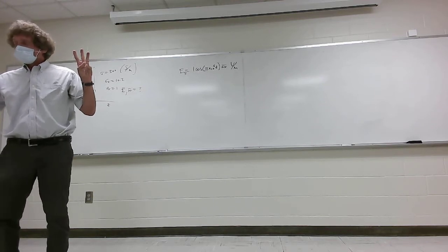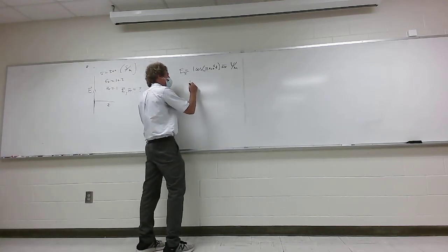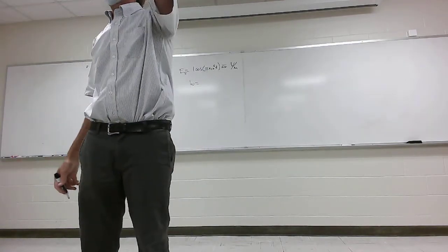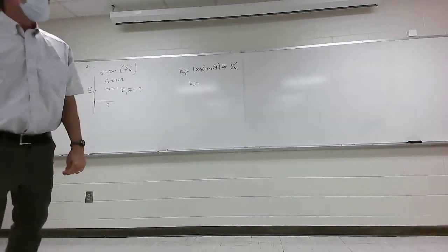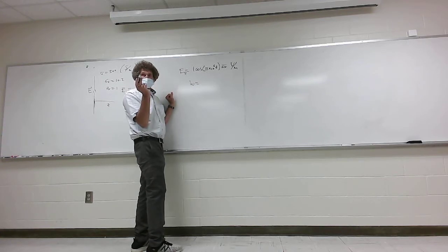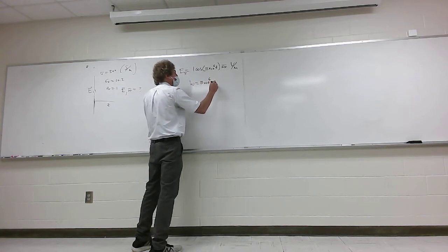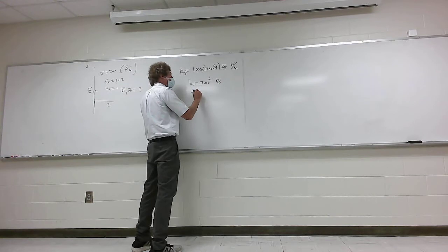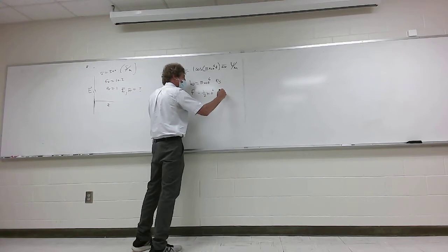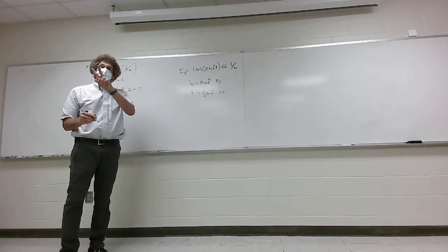Before we do that, we have to ascertain the frequency of operation, omega, by looking at this. What's omega by looking? It's pi times 10 to the 6. It's the coefficient of t inside the cosine argument. So omega is pi times 10 to the 6 radians per second. And if we wanted f, it would be 1/2 times 10 to the 6 hertz. Just putting them both down for you.